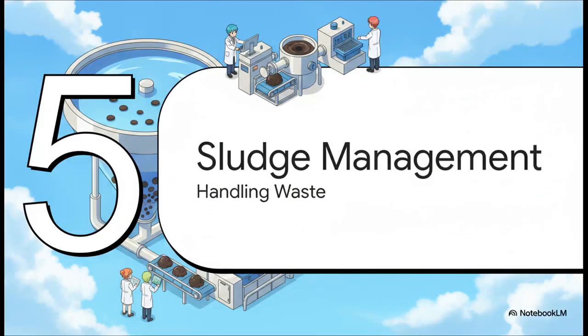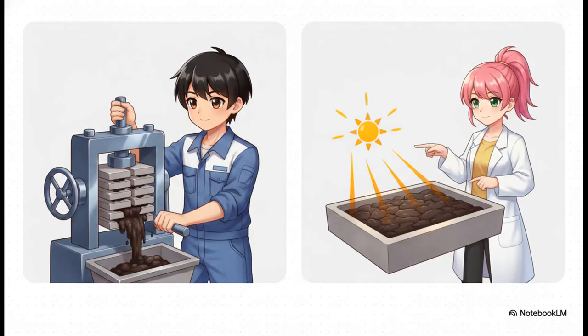Section 5. Sludge management. Because what gets separated from the water has got to go somewhere. So those heavy flakes of pollutants eventually settle down to the bottom of the clarifier tank. In massive industrial plants, you'd see these incredibly expensive automated dewatering screw presses handling hundreds of kilos of sludge. But for a 5,000-liter mini ETP, you have two super practical options. Option 1 is a straightforward manual filter press to just squeeze the water out. Option 2 is even simpler, a small sludge drying bed, where the wet sludge literally just dries out in the air. Both methods really highlight how operationally accessible the scale is.